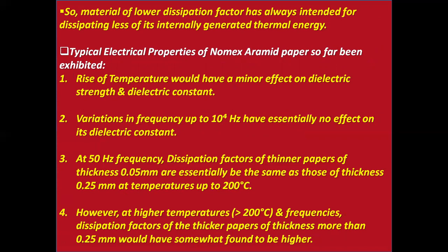Typical electrical properties of Nomex Aramid paper exhibited so far: Number 1, rise of temperature has a minor effect on dielectric strength and dielectric constant. Number 2, variations in frequency up to 10 to the power 4 Hertz have essentially no effect on its dielectric constant.